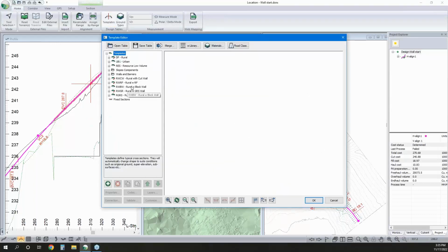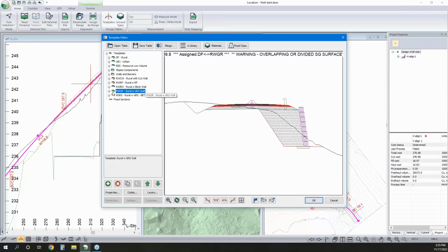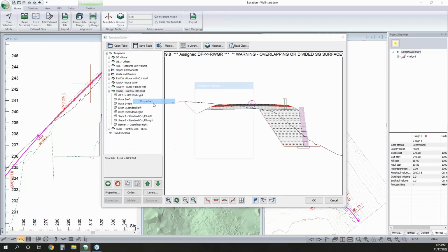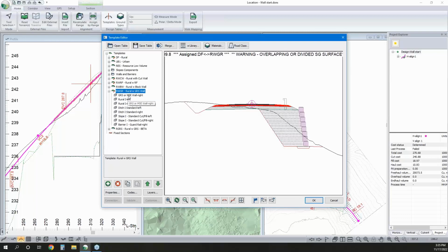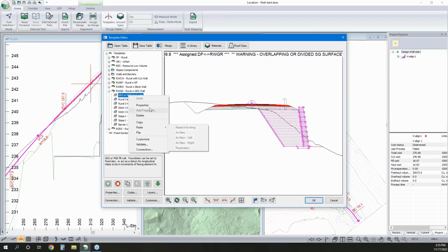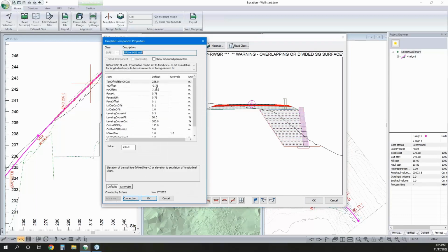But right now, if we go in here, we've got our parameters. So I'm going to scroll down here and we've got our tieback vertical spacing. I use the term tieback because the text style could be grid, could be something else used as an anchor. And here I've got that set to be every 25 centimeters.